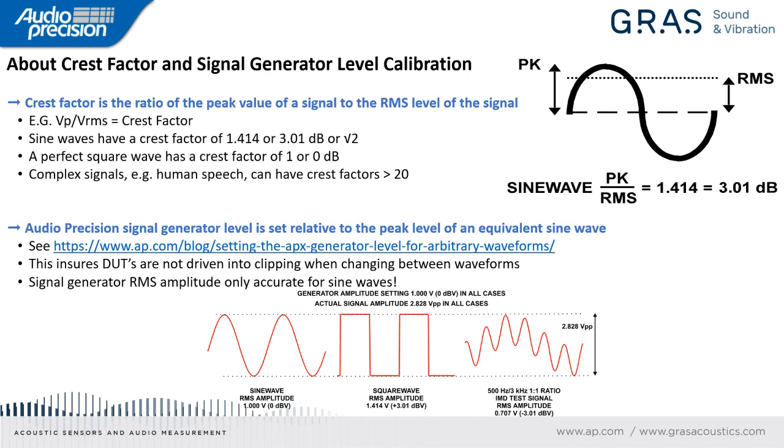And this is a very common unit you'll see in reference to room acoustics or room noise. If somebody will say, oh, the sound level in this room is 52 dBA. And if they wrote it all out, they should say 52 dBSPL A weighted, but that is very, very often contracted to dBA.